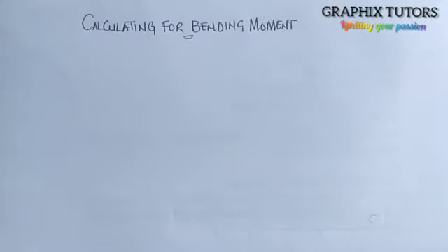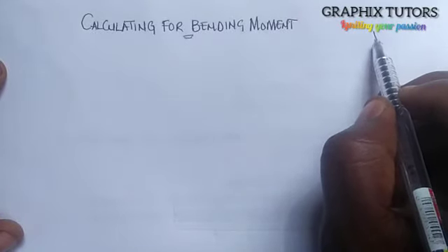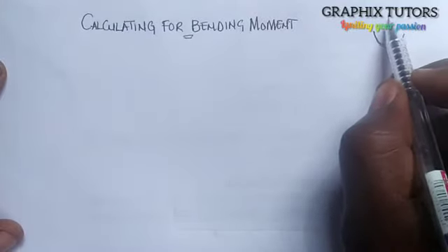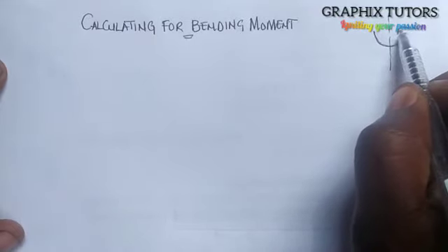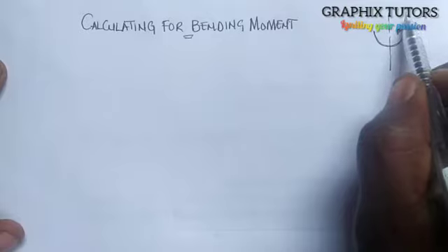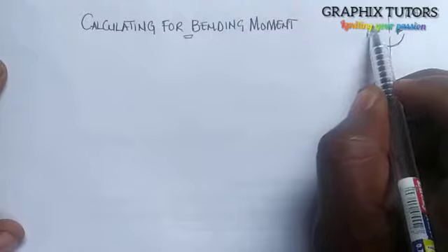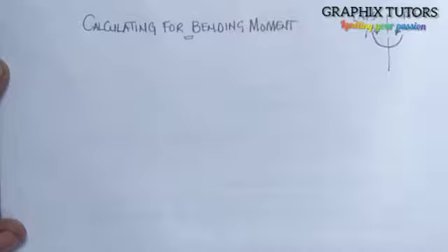In terms of bending moment, we have what is called hogging and sagging, right? We say if you have this way, it's more like this, and if I section it, so if the force is anti-clockwise at my right hand side, or it is clockwise at my left hand side, you see the bending moment is positive, right?